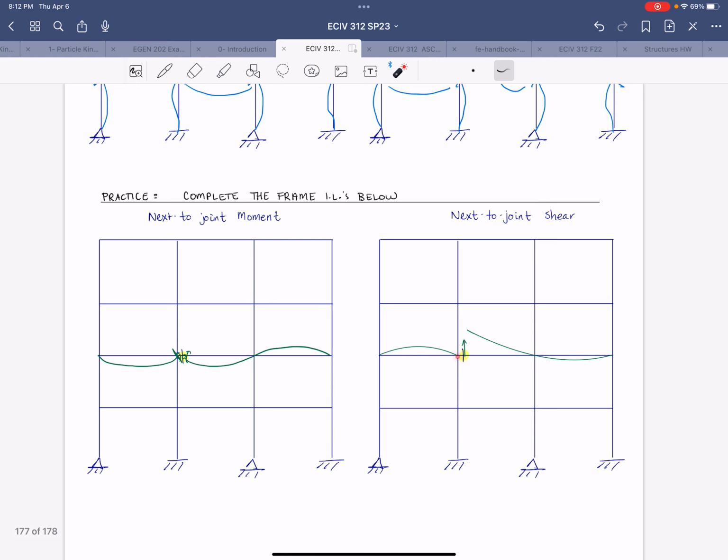The other side, in this case the left side, wants to go down, but it can't because there's a joint there. So we treat that joint as a support, draw that influence line, right? The slopes would match, right? So again, your sketch doesn't have to be perfect, but we remember in our heads that the slopes here match. So that means that it's got to be an upward deflection, right, in order for the slopes to match.